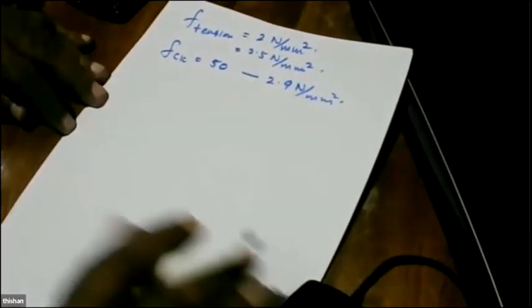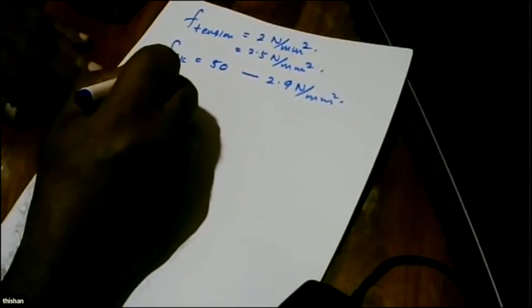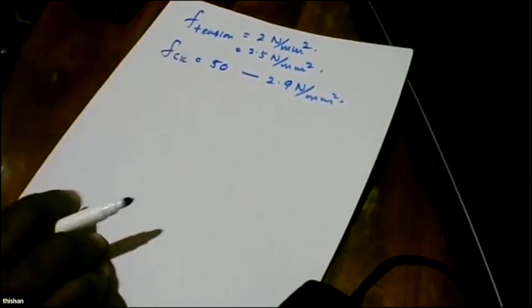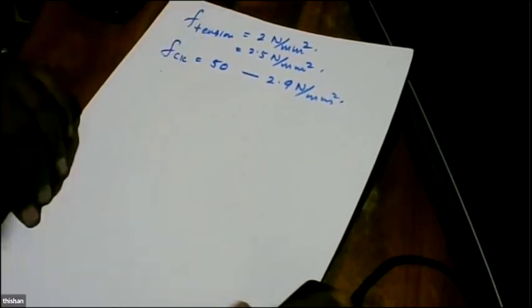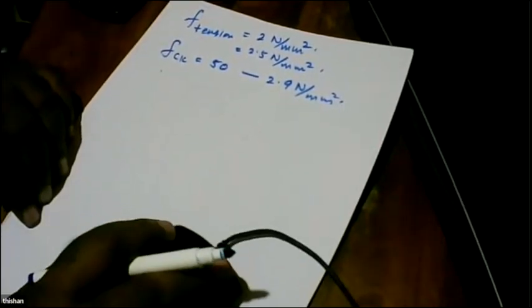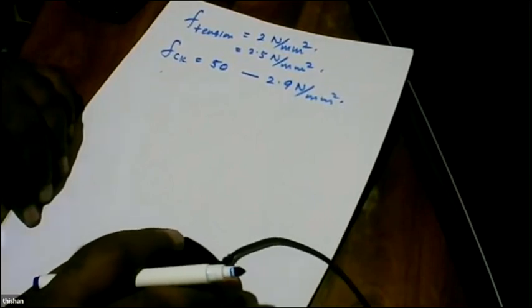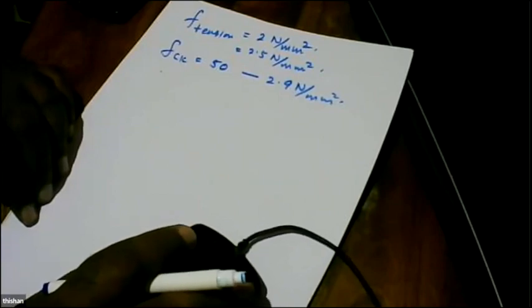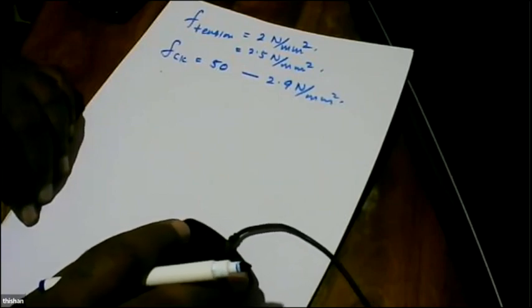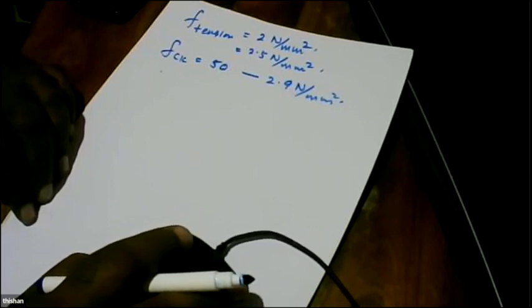Now we are talking about 40 to 50 concrete, and in that one the allowable tensile stress is about 2.5 megapascal.